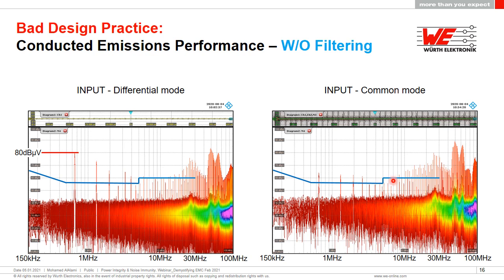But there's also common mode, and the common mode is coming up further up in the frequency spectrum. So this is the other area that we need to concentrate on as well. So this is where it gives you that extra bit of visibility, and using a decent piece of equipment will give you that information ahead of you going into any form of even de-risk testing at an EMC test lab.